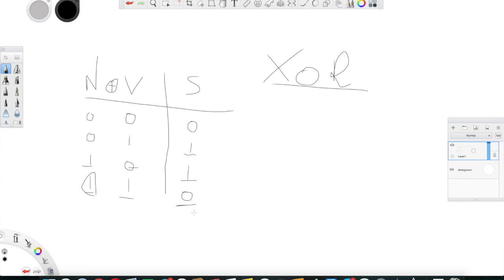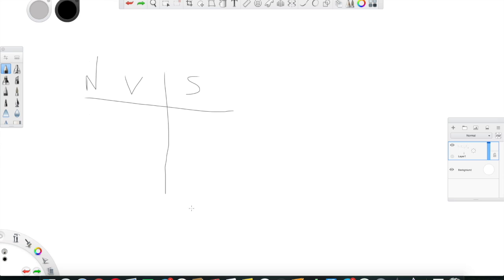And therefore, the sign bit will be 0, and this operation is the exclusive OR of the negative flag and the overflow flag. Now we are done with the sign bit, and that's why I kept it to the end, because we had to understand the negative and overflow flag bits at first.